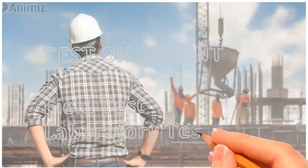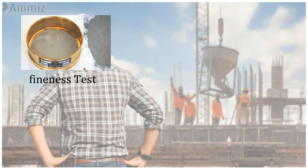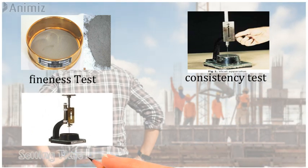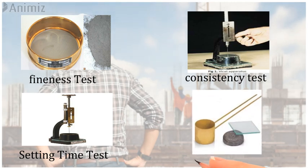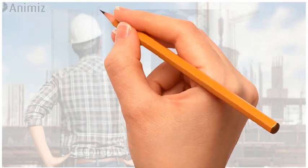Now we have understood there are various types of cement, but what are the tests which we conduct in the laboratory and on the field? There is the fineness test, which needs to be conducted to ensure the quality of cement. Then there is the consistency test. We also have to understand the final setting time and initial setting time tests. And the soundness test is equally important to understand. One of the major tests is the compressive strength test.